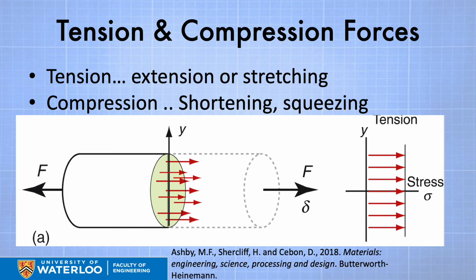And we're either stretching it, following the PL over AE rule: load P times length of the element L, all divided by the modulus of elasticity times the area. That tells us how much it will stretch. Tension stress, of course, is just the force P divided by the area A. Compression stress, the same way.